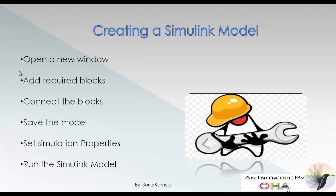So let's create our new model. To create a new model, the basic steps are: first, open a new window, then add required blocks, connect the blocks, save the model, set the simulation properties as per your need, and run the Simulink model. In this way we will start our simulation model and we will create a lot of models.